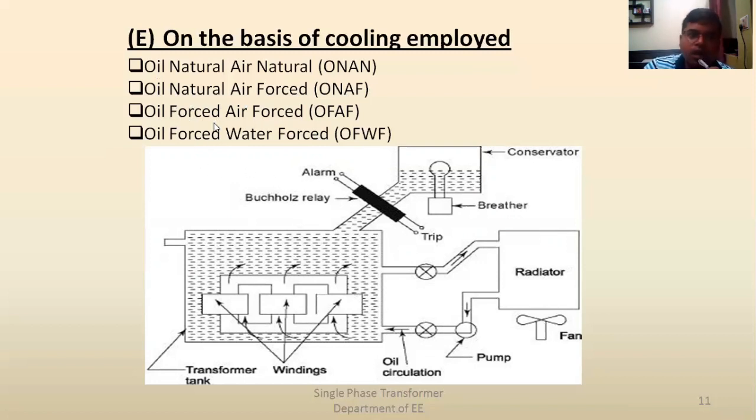That means oil forced, air forced. This pump will start, which will forcefully circulate the oil inside the tank through the radiator. So this fan is also on, this pump is also on. So this is called oil forced, air forced. And the last is oil forced, water forced. Sometimes in special cases, water is also used for cooling of the oil through water sprinkling. This is not very common, but these three are very common.